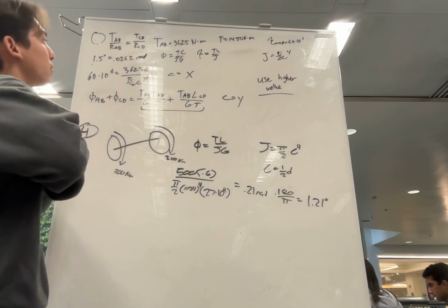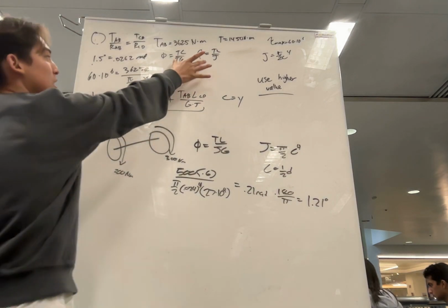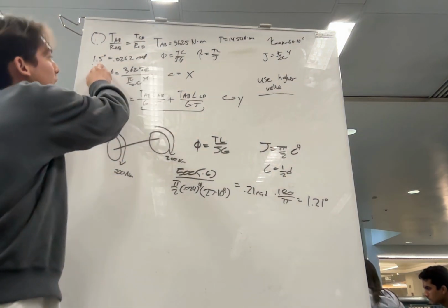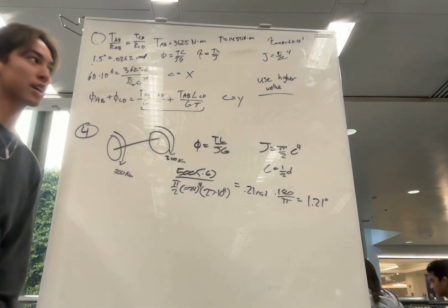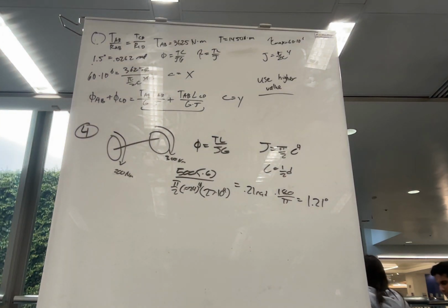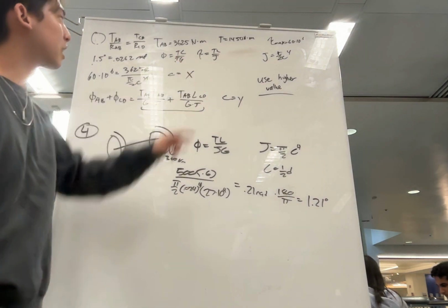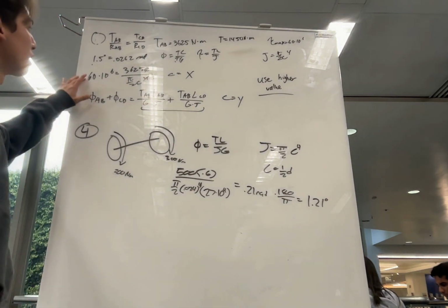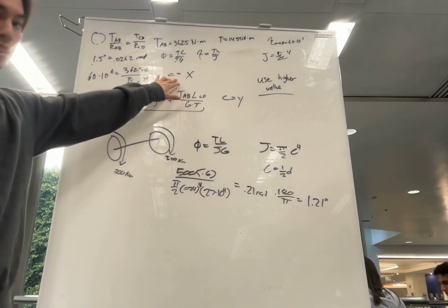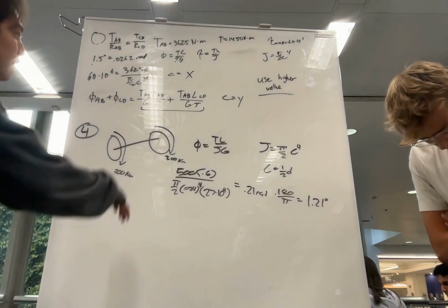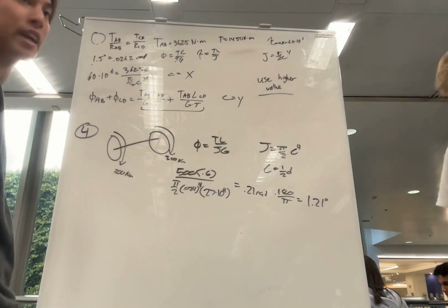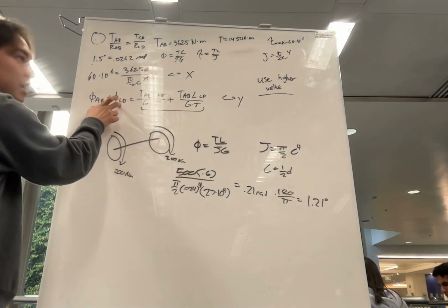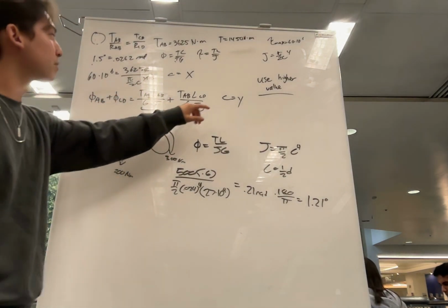So we have 2 equations that can solve for this diameter. We have one using the angle it gives us, and one using the maximum torsion it gives us. We're given every value for those equations too. For the torsion one, we get a value if you plug in all your values. And for the angle one, we do angle of AB for one length and CD for the other length, and you add both of the angles to get your final angle.